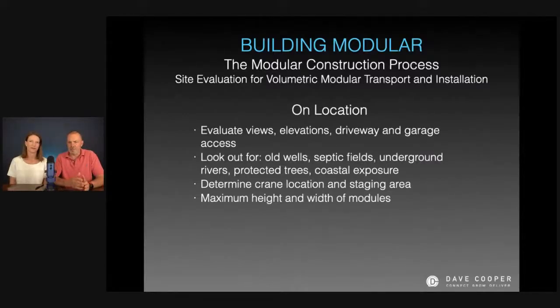But again, on location, you want to evaluate the views. This is another opportunity to look at the next step. What are we going to build here? How can we build? Where's the driveway, garage access best located if you are a design build firm? If you're the architect for a large project, same thing. While you're on site, was there an old structure there? Were there wells? Were there septic fields? Try to know that. You don't want to drive these trucks over an old abandoned septic.